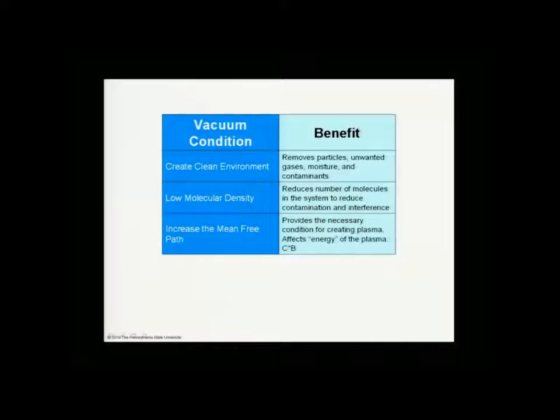Low molecular density. By reducing the pressure, we have fewer molecules and atoms. If we have fewer molecules and atoms, then we obviously reduce contamination, and we reduce the possibility that those molecules and atoms can get involved in our processing.